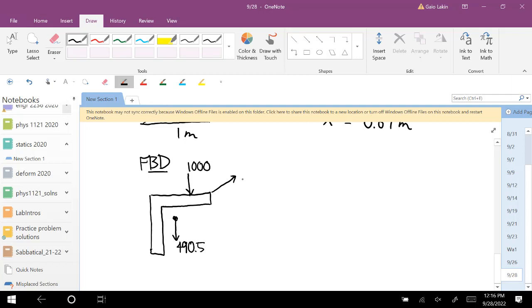And then you have a cable tension, and the pin joint down at this corner applies a full unknown force vector, so I'll call that R. Do we have any chance of solving this? If we have more than 3 variables, we don't, but in this case we have 3, so it should work out unless some of the equations are linear multiples of each other.